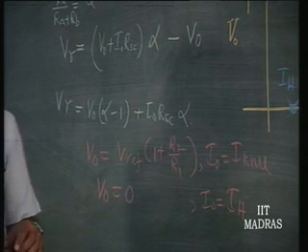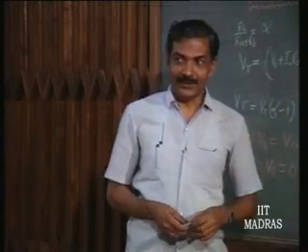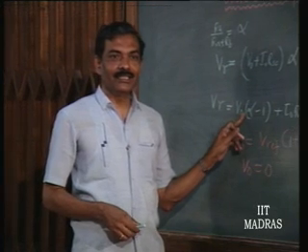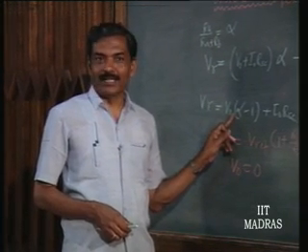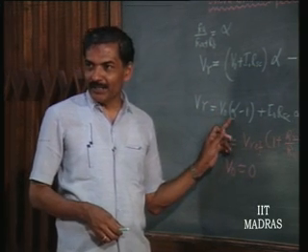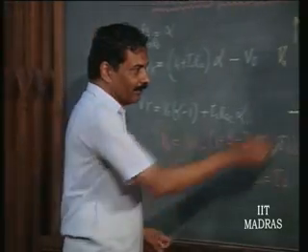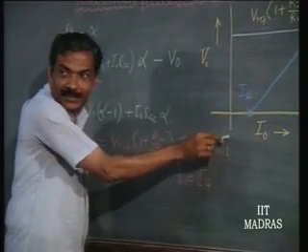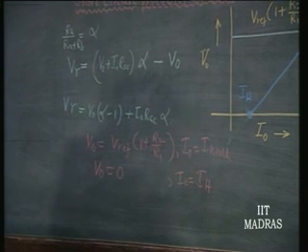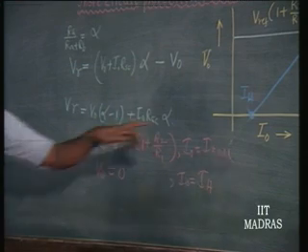The question is, can you make it very, very small? What is it that is going to cause problems? One thing that you have to see is alpha has to be less than 1. In solving this equation, you must have alpha less than 1. So, actually when I naught is 0, it should intersect at the negative value, which is magnitude of V naught into 1 minus alpha. That is that point.